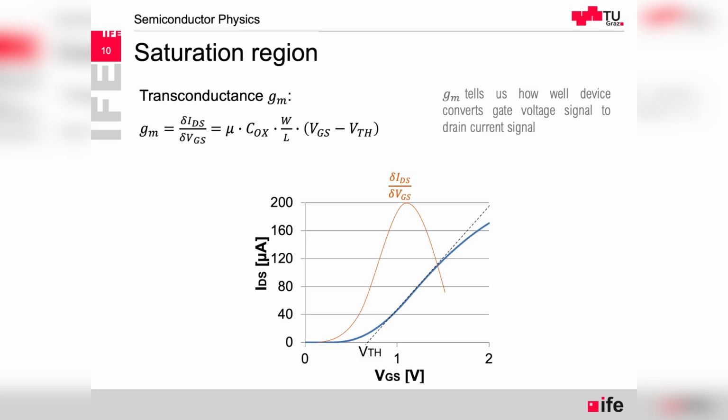So we will apply a small signal from some sensor at the gate, usually over a capacitance, or in a differential structure, because we also have to make sure that the gate voltage is biased. So that's maybe a slightly more advanced circuit point of view on that.